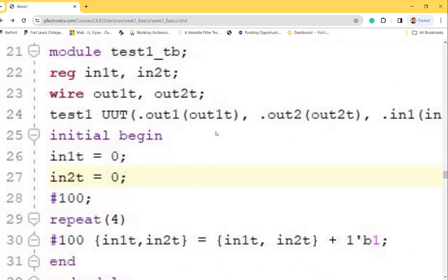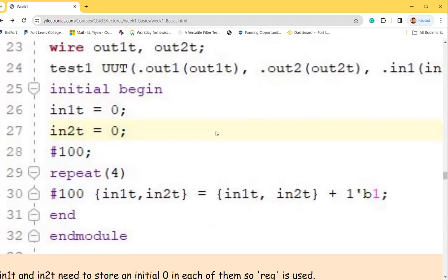Yeah, it's going to be 200 nanoseconds after that. However, after the first time of a flip of the data, it's going to stay here, repeating this for 3 more times. And you're only having a 100 nanosecond time delay instead of 200 after that for all the changes. Does that make sense? You have to stay at the previous data level, the voltage level, first for 100 nanoseconds, and then do some changes according to the logic.